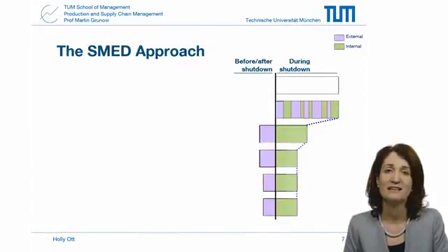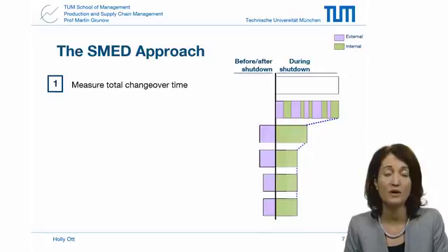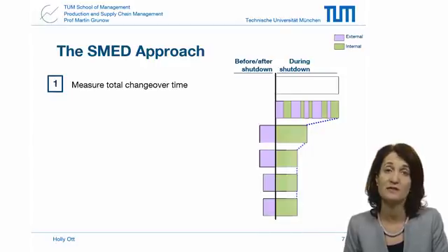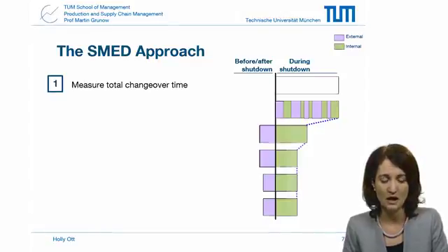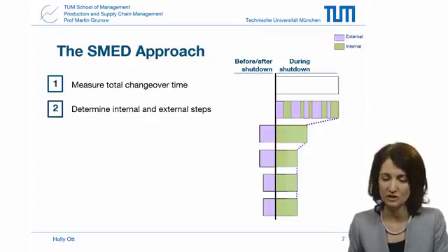And here we look at the SMED approach. There are 6 different stages. Stage 1 is to carefully analyze all the tasks that are part of the setup time, part of the changeover time. And here, it's very much advised to make a video, or even several videos if there are different shifts. So you want to measure the changeover by checking to see which tasks are internal tasks and which are external tasks.